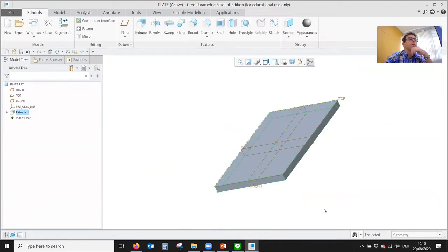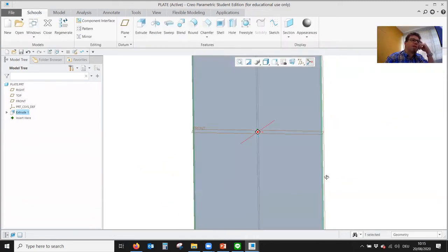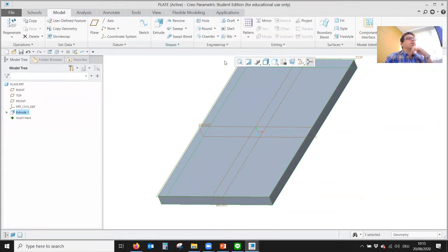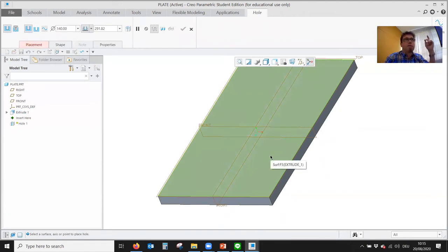So now I have to do some calculations about a good pattern for screws, maybe 20 millimeter distance, or let's say 50, we don't want to have too many. So I'll make a first hole. I'll do that by using one hole. So the beginning of a pattern is one feature, and what is important, most patterns you pattern by dimension.